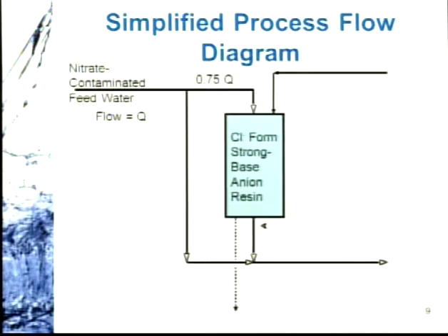If your raw water nitrate concentration is just at or just over the nitrate MCL and you want to target commonly what DPH would prescribe, about 80 to 90% of the MCL on the treated water side, you could treat the process flow to a very low concentration and allow the untreated water to blend and bypass. So that's an important step shown here with that bypass water.